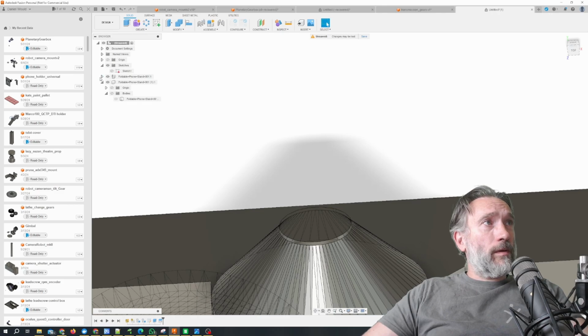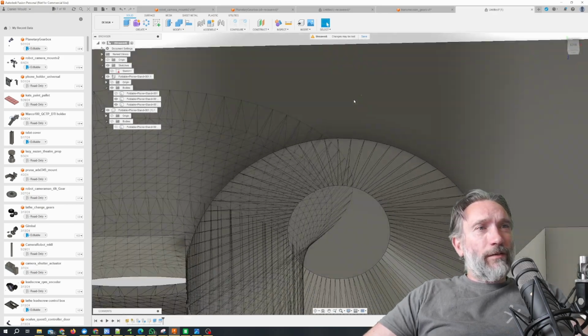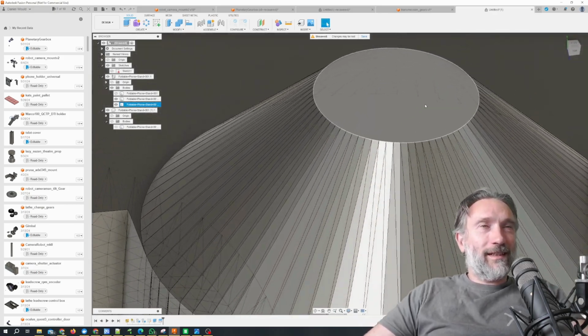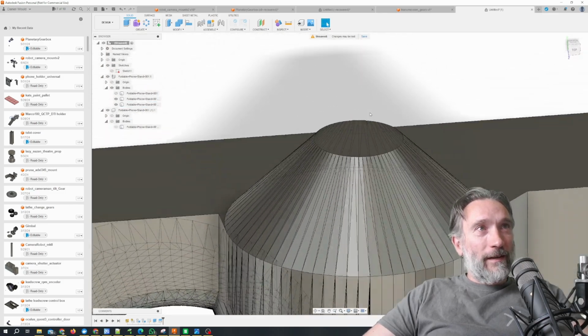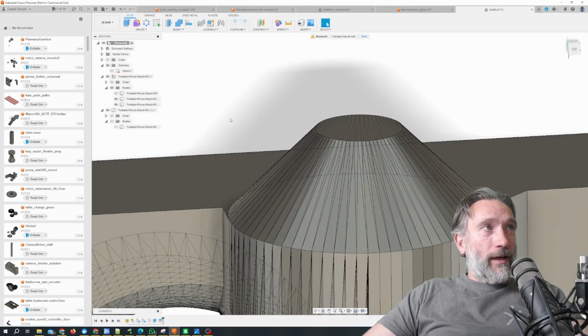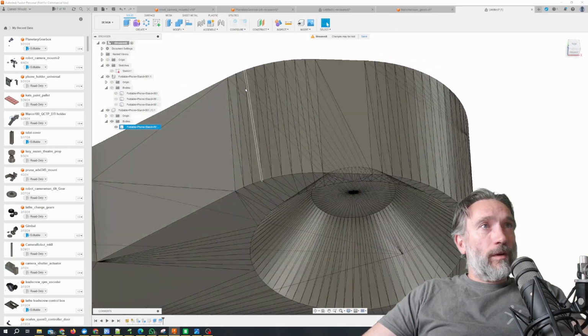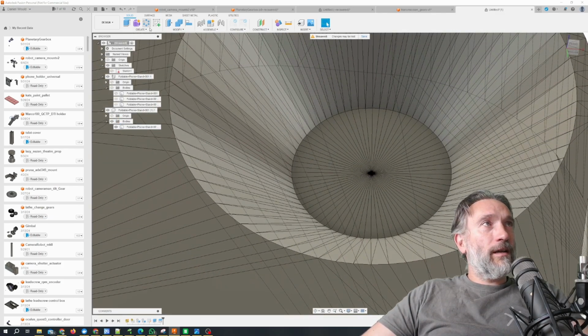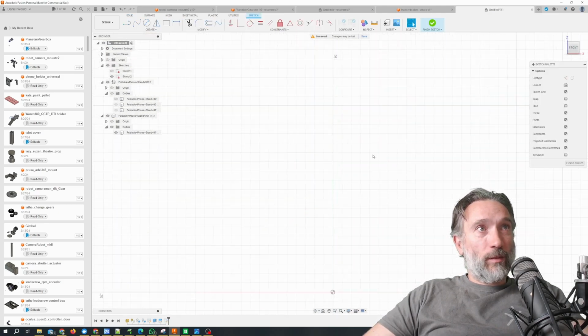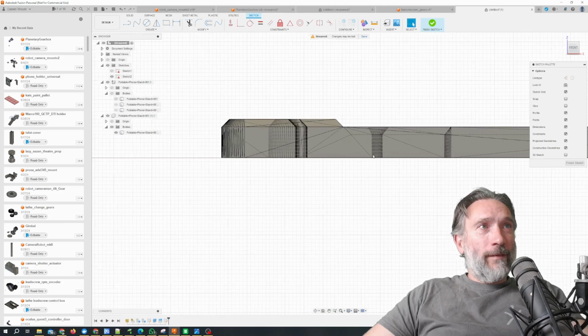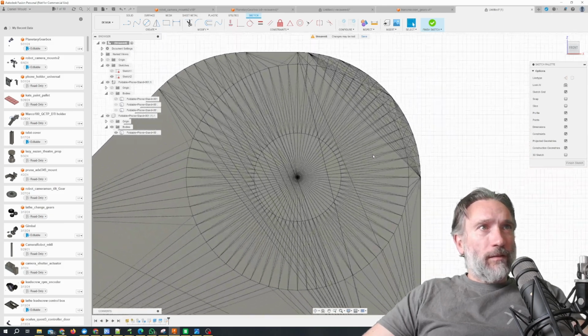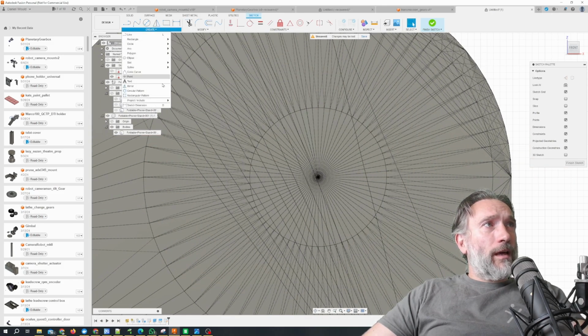Not that one. Right, now we have that as a separate body. Right, so we get rid of that. So we've sort of done this artificial extend and then drop it off, but now we have a nice flat circle that is a real piece of geometry. And now if I turn the other way around, we'll do the same thing in here. So this will give us two surfaces that we can reference that have a center point that we can define an axle off. And this is something that you end up doing a ton, so you get quite used to it.